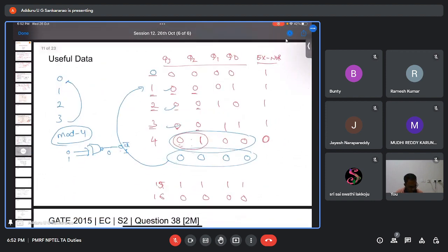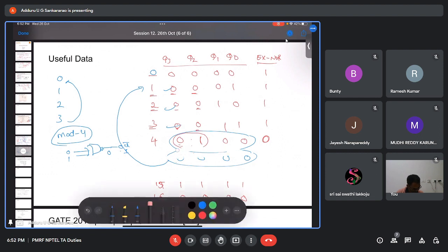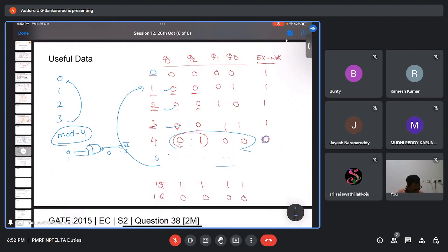So if it is the synchronous one, the output of the XOR gate after the fourth clock pulse is 0, but still they cannot clear it. The fifth clock pulse should come, then only this will be cleared. The clear inputs will be effective whenever the next clock pulse comes. Is that okay?